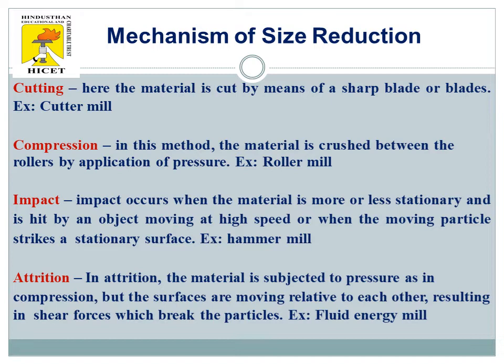The third principle is impact. In this principle, the material is more or less stationary and is hit by an object moving at high speed, or a moving particle strikes a stationary surface. The example for this principle is the hammer mill.